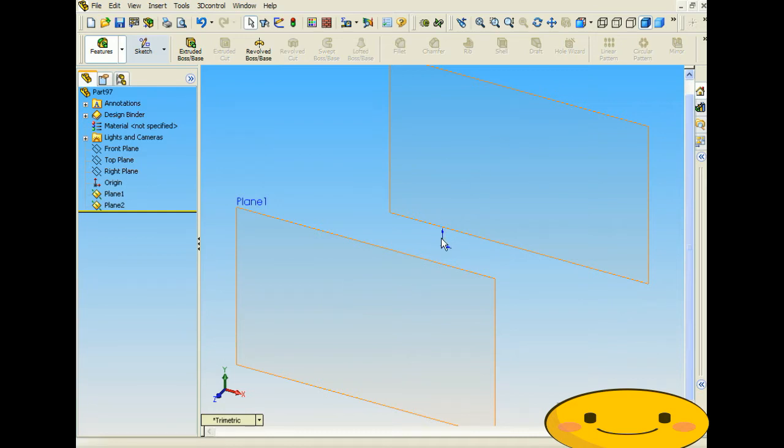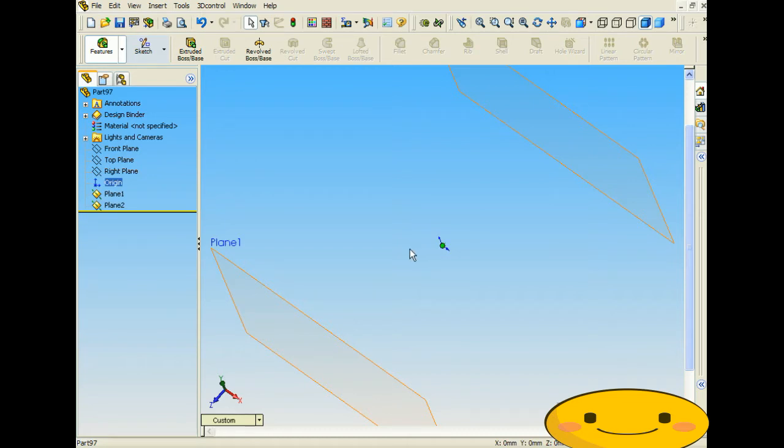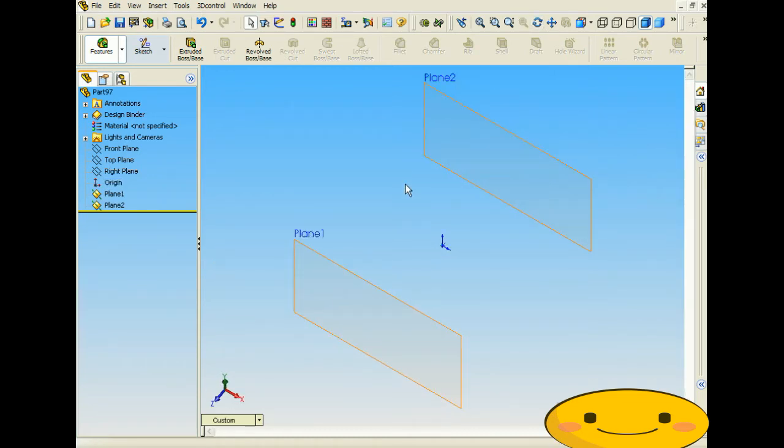So what we're going to do is create a sketch on this plane. We're going to center those sketches on the X and Y, extrude between the two sketches, and then change the Z direction, so the distance of both of these planes, to create the center of gravity and make the center point right on the origin. To start off, we have a 200 millimeter distance between the two here. So if you wanted your part to be 200 millimeters long, make sure that in between here is 200, because after, say we have to move this 5 millimeters one way, this plane's going to be 105 and this plane's going to be 95.